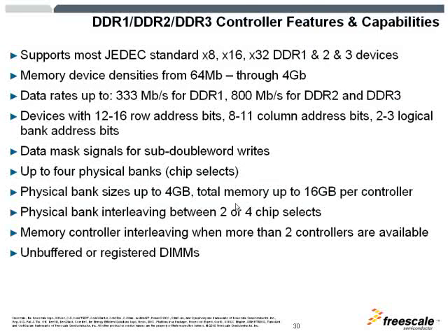Please defer to the datasheet for the device to find out what is the maximum DDR data rate operations for that specific device. The number of rows and columns are also supported to the maximum, and the data mask signaling is also supported for when less than sub-double word writes are written.